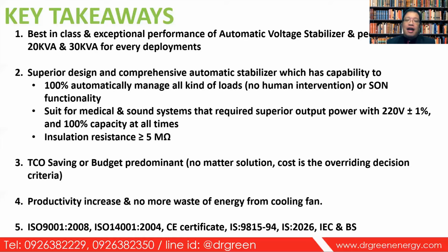The next one is about safety. The insulation resistance should be more than 5 mega ohm. 5 mega ohm is a very safe value, very good safety, and can protect you from any possible accident, or any possible thing that can happen. So for insulation resistance, we recommend at least 5 mega ohm. Carefully check the technical specification for this point as well.